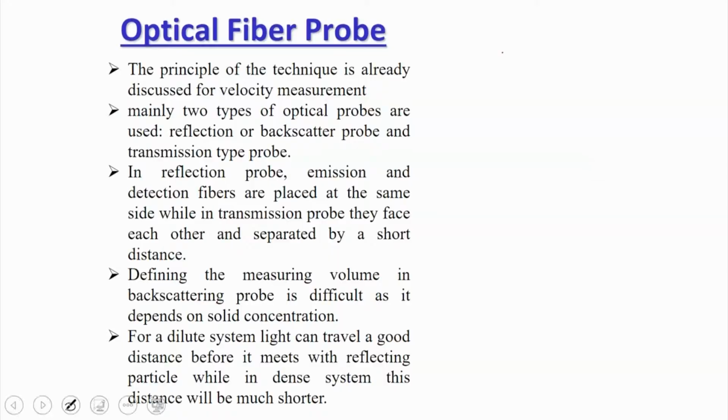The only thing is there is a little bit of difference in the way the optical fiber probe is used in the volume fraction measurement. There, in a simple way, we were taking a probe of 2 different lengths, say this is one probe, this is the other probe, and we take the lengths different. If a bubble is coming, once it comes here, it will touch here, it will give a peak, and we will identify that this is a bubble. We will record the voltage; once the bubble comes, the voltage will change.